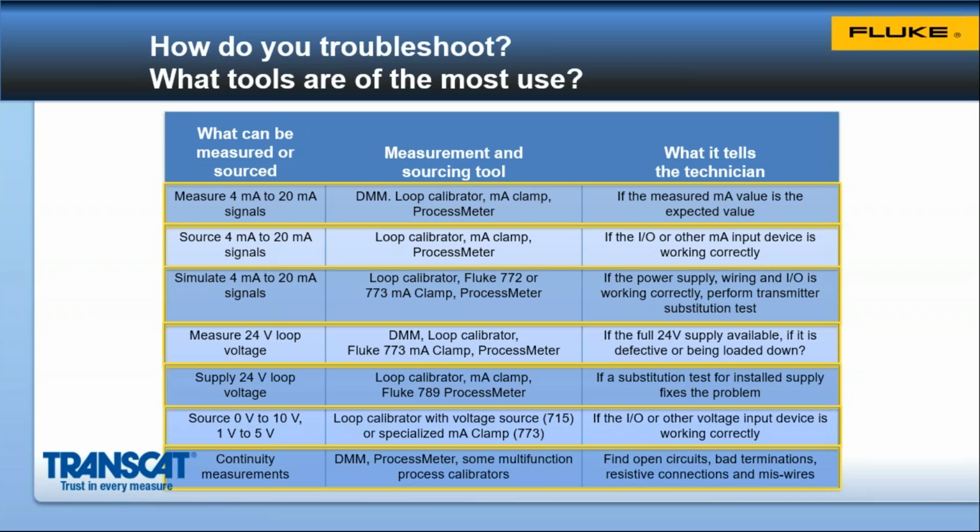In fact, in a couple of our calibrators, we refer to milliamp simulate as transmitter simulate, as the function is designed to inherently replicate the operation of a two-wire transmitter in regulating a 4-20 milliamp signal. And we'll discuss that function in a little bit more detail when we get to the milliamp simulate troubleshooting function. But essentially, it's a very powerful function in a loop calibrator.